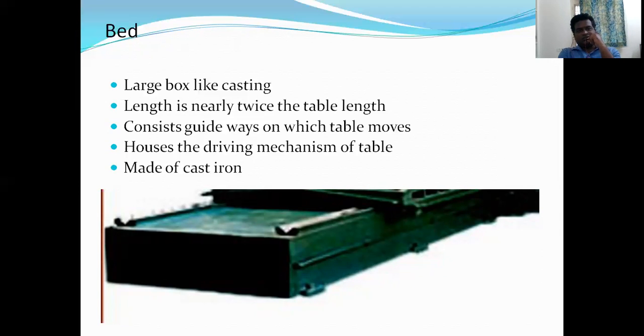So for this, the bed is like a box-like structure. It is made with casting, and its length is nearly twice the table length. Why? Because on this bed, the table is reciprocated. On this bed, it has the guideways, so on these guideways, the table is moving, reciprocating.